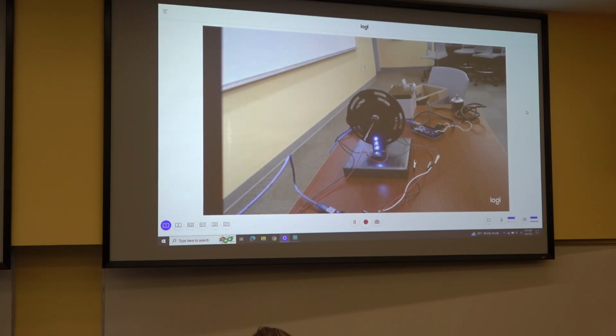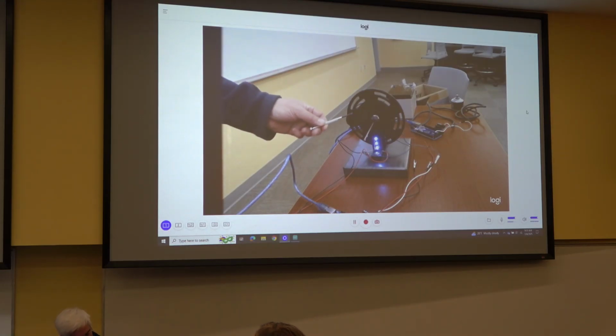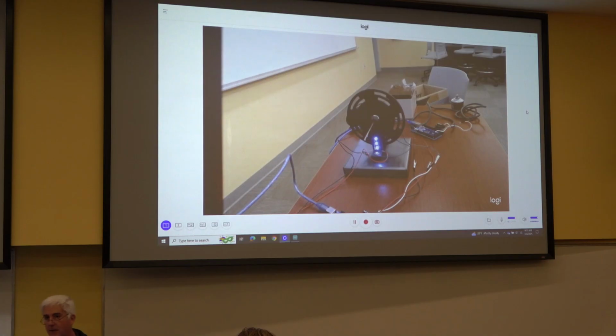And you'll notice that they don't line up. And there's a reason for that. These slots are exactly 1/4 of an interval staggered. It's called quadrature codes.